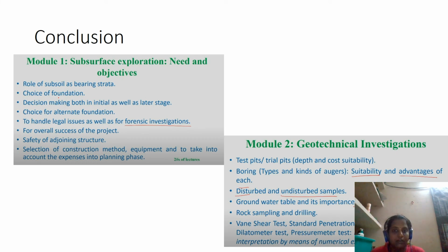Some years ago there would have been a well, which has now been filled with debris and closed, and they would sell you the land. So we have to know what is lying below our ground, and then only will we be able to know what kind of foundation we can go for, and what the alternate methods could be if the soil is going to be poor, such as foundation or ground improvement techniques we can use.